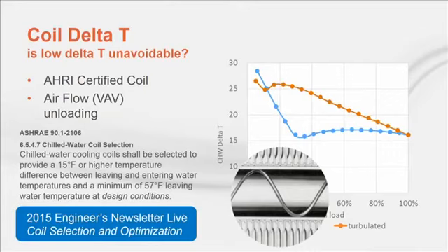But with this type of heat transfer performance, the pump energy penalty quickly goes away at part load. This can provide more efficient annualized operation. Let's set this aside for now, but we highly recommend the consideration of internally enhanced tubes in variable flow chilled water systems.